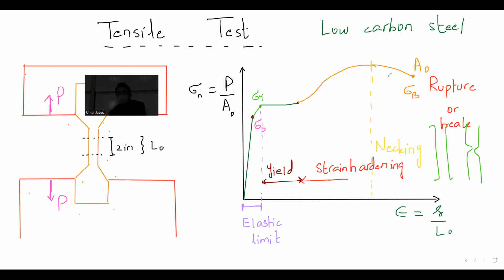Okay. And for students who are saying, if the necking happens, then the area decreases, then why on earth does the stress decrease? Anyone who wants to please explain to us? Yes, the area decreases substantially. So why, because area is in the denominator in stress, in the necking zone, is my stress decreasing? Look at the denominator and tell me then.